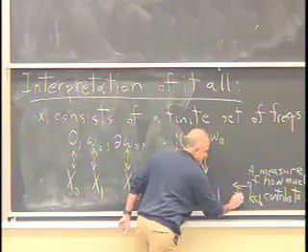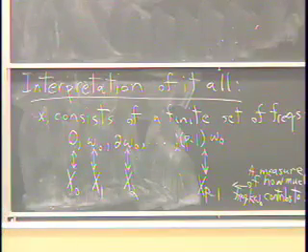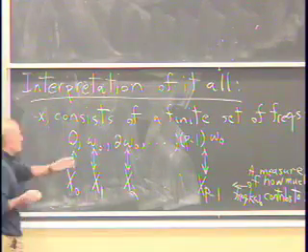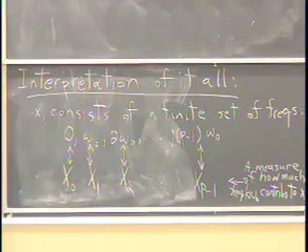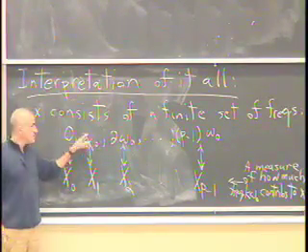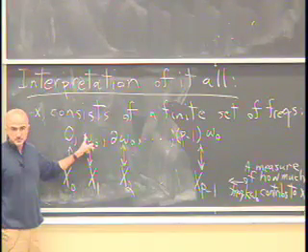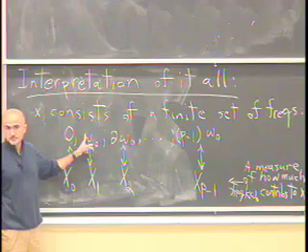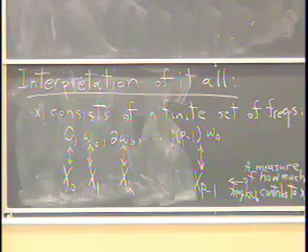Let me emphasize this is the frequency. So each xk, the kth coefficient, tells you how much of the kth frequency is present in the signal. Okay? So if a particular xk, let's say x1, happens to be 0, that means omega naught is a frequency that's not manifested in the signal. The signal does not contain that frequency. Any questions on this interpretation? This is very important.